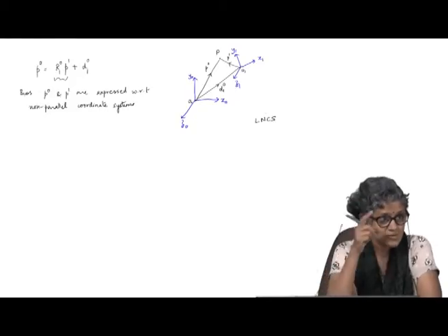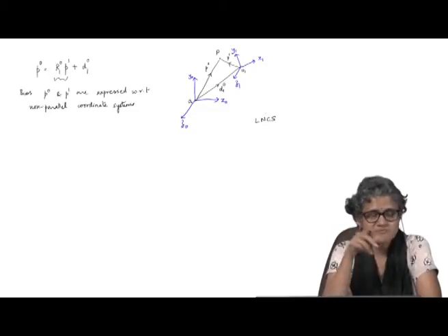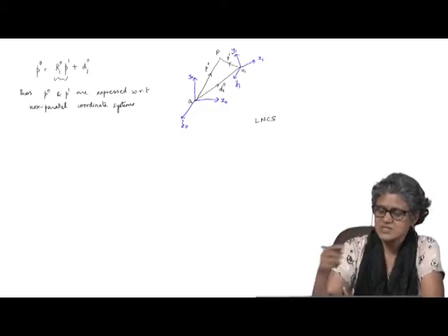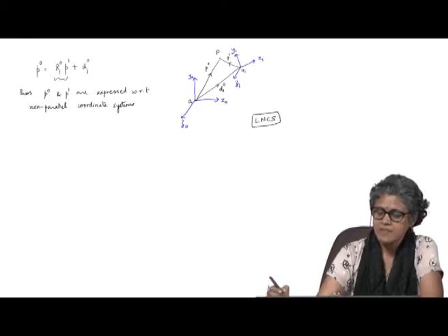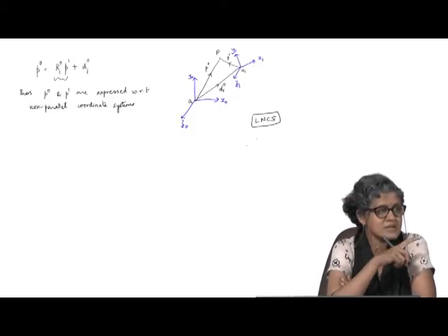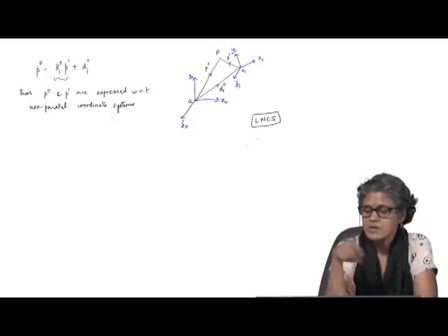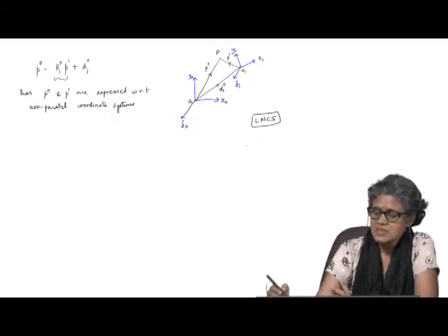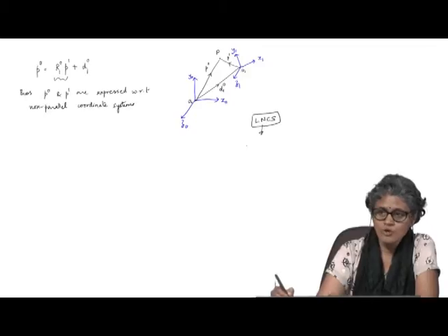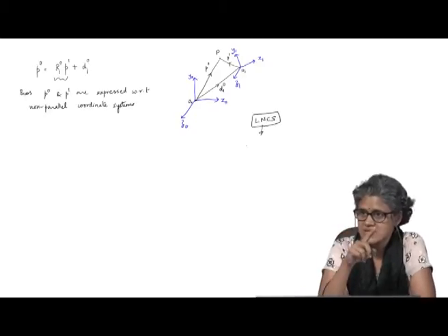We expressed all those position vectors for the points of application of the forces, etc. So, in each case there we took a coordinate system with the origin at the CG, but we said it remains parallel to the global coordinate system. Okay. So, that is the case where you have a non-rotating coordinate system. So, that is when you can add those vectors directly.